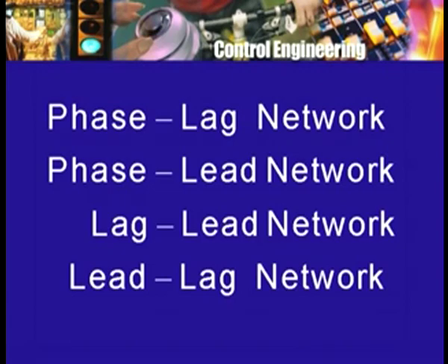So, when amplifier design was in its heyday in the 1930s and 40s, people tried all these kinds of networks, phase lag, phase lead, lead lag networks, and they were actual electrical networks consisting of, as far as possible, resistors and capacitors. Resistors alone will not give you a variation with respect to frequency, so you needed capacitors. In the beginning, one also did not mind having inductors, but then one wanted to do without inductors being heavy, etc.